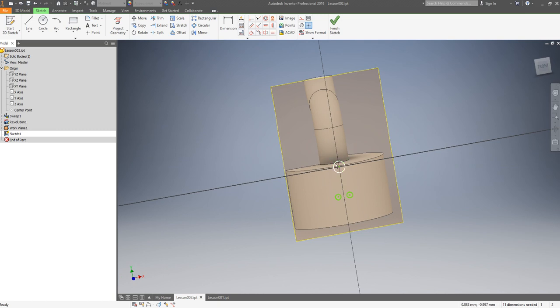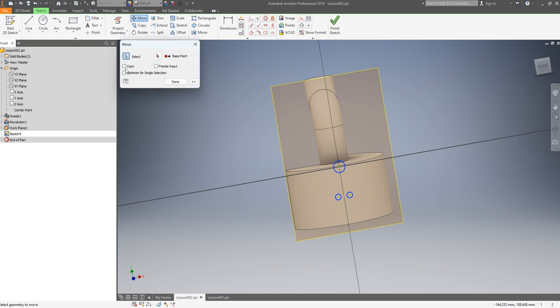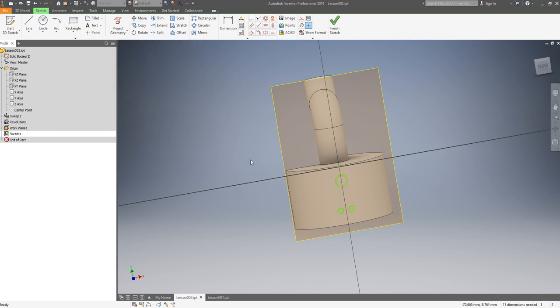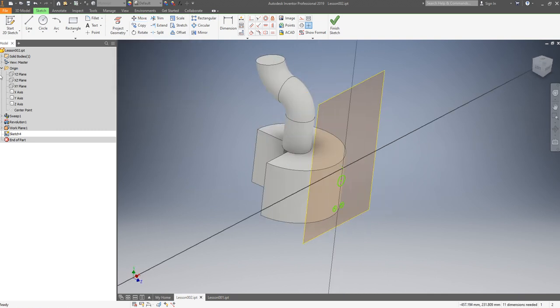So, if we want to move the geometry, copy, or we just click that, select Control, multi-selection, then it's going to be very similar as AutoCAD. We click Move, and what's already been selected, the base on this point, down. Done. So the geometry is done.